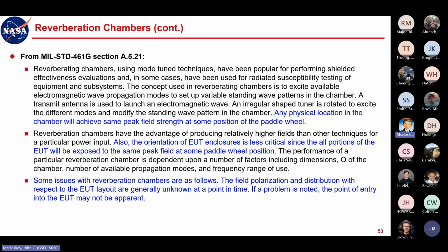Obviously, we only do that up to 200 megahertz. But if I'm injecting on a specific cable, and I see a susceptibility while injecting on that cable, then I can conclude that there's something about that interface circuitry running in that cable that the susceptibility is associated with.